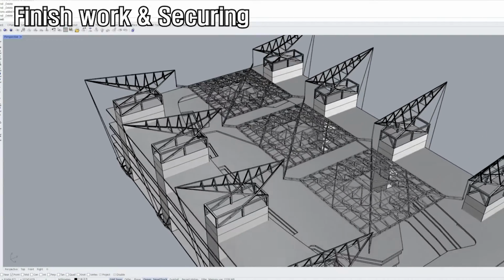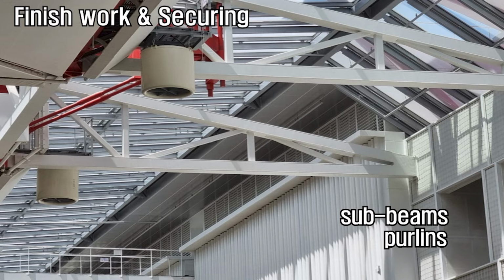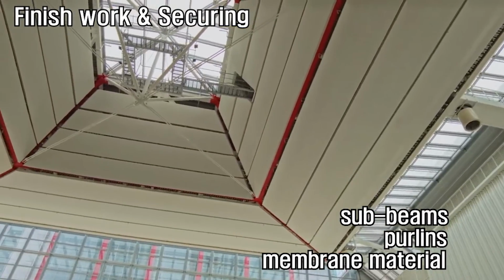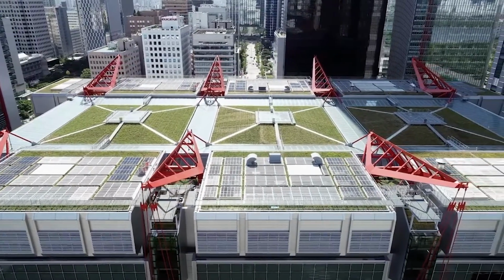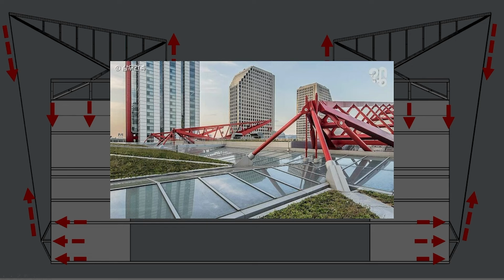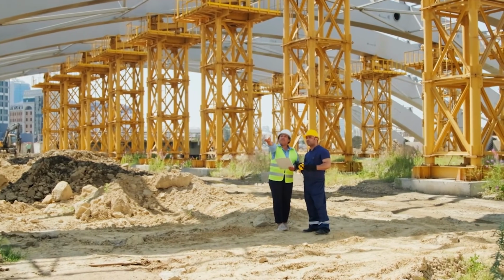After the bands were dismantled, sub-beams and purlins were installed on the truss, and the membrane material was overlaid on top of it to complete the Hyundai Seoul's roof as we know it. The crane and the trusses were very heavy for the roof structures, but they used an unusual load distribution method without columns and using tie rods, which required more detailed construction management than conventional buildings.